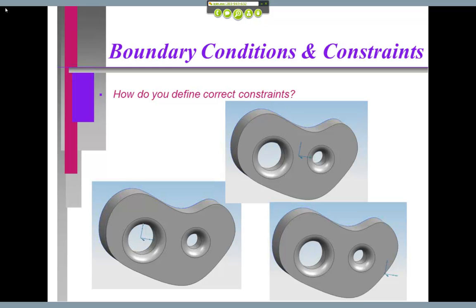Pin it where? Okay, so would you maybe pin just the bottom, the center of this, because you're really just impacting it up here and you want to see the effect on all of this thing? If we constrained it right up here at the upright and we impacted it there, what's it going to do for us?